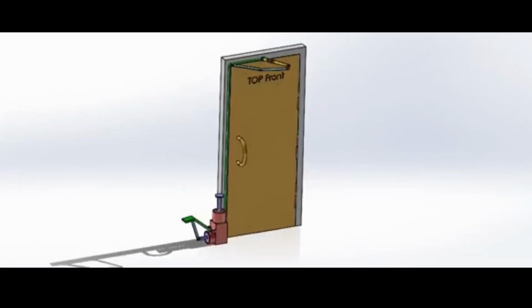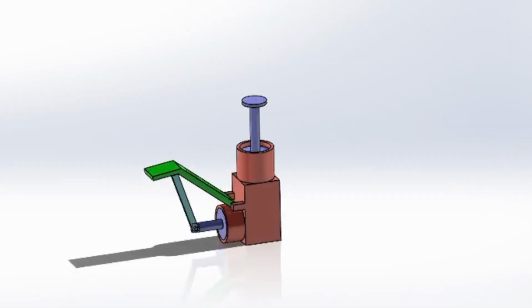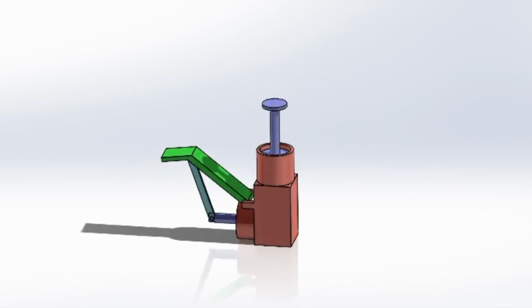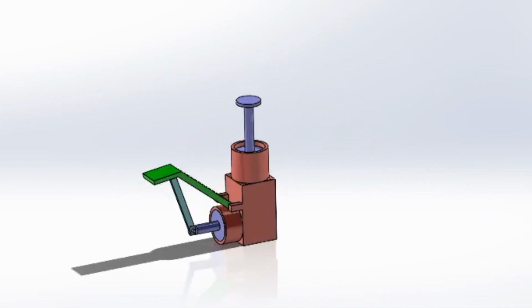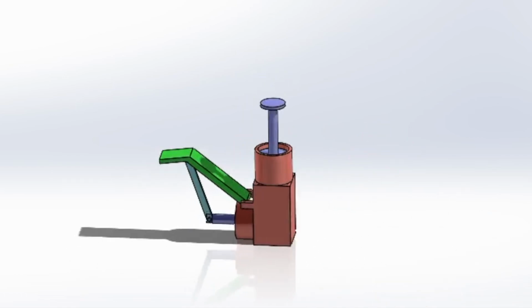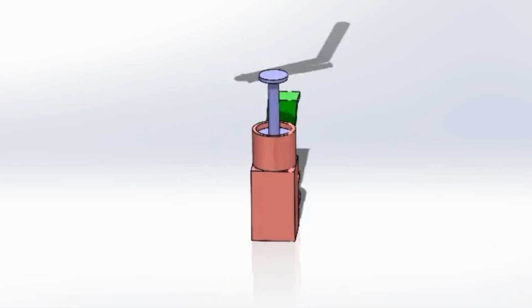Now let's further discuss what each of these subassemblies are responsible for. The piston subassembly has 2 piston cylinders that extend outward. The cylinder on top of the base is meant to be pushed downward using your hand. The cylinder on the bottom of the base has a stepping plane that is linked to a piston arm. This piece is meant to be pushed down by stepping on it. Both of these pistons are part of a larger hydraulic system that controls the whole mechanism.